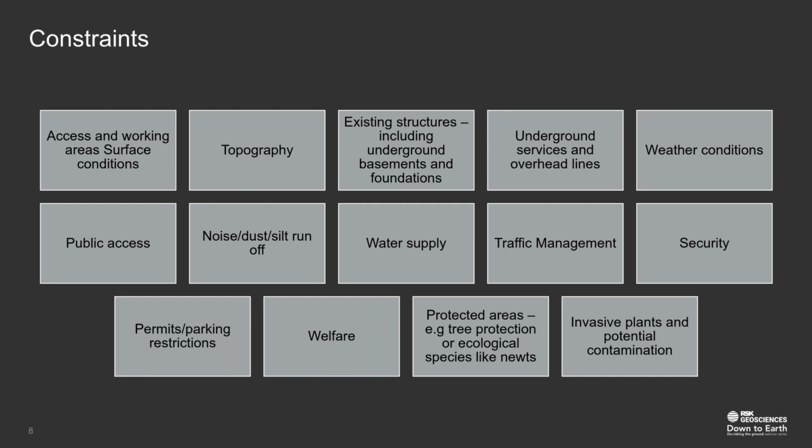Do you have a water supply? This is a big thing that often gets forgotten, but most drilling techniques will need a water supply to be able to function. So if there isn't one on site, have a look around and walk around. Is there any hydrants that you can get permission for?